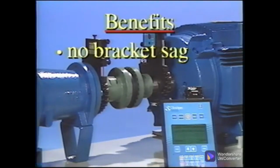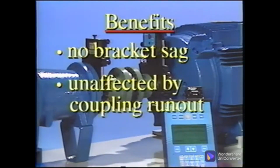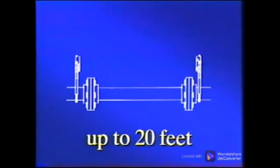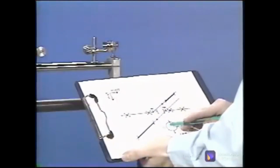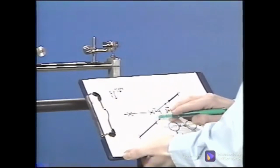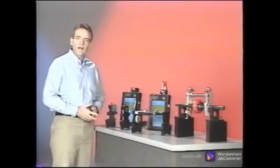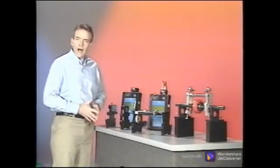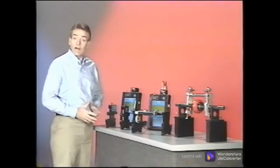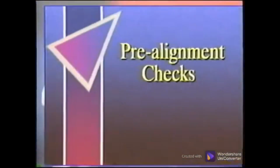Because there is no bracket sag, it is unaffected by coupling runout and any axial float in the machine. The laser system can be used over longer spans than the reverse dial method, but its accuracy can be affected by airborne particles. When an alignment analyzer is not available, the machine moves must be determined by graph or mathematical equation. Whatever method you use, there are common steps that must be completed before actually performing the alignment procedures. These are explained in the next section.